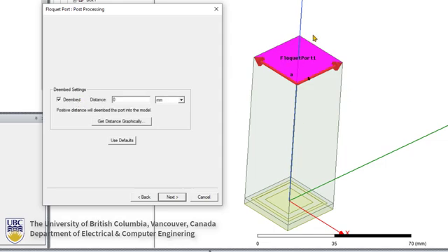And this is the de-embed settings. We need to transfer the reference plane of measurement from this Floquet port plane to right at the top, or right at the surface of the AMC. So we need to find out what reflection phase is occurring right at the interface of the AMC and the air. That's why we need to de-embed this Floquet port from this plane to the top of the AMC. And the distance between them is box H minus SH, where box H was the height of the box and SH is the thickness of the substrate.